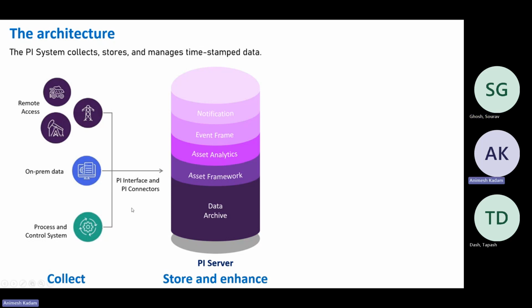So one copy, the interface copy, is where it is installed, but the configuration details are different. It is not only one. Suppose you have 10 interfaces. All 10 interfaces' configuration details will be stored inside a module database, which is a file format. Where will that database be? On the PI server itself, under data archive.